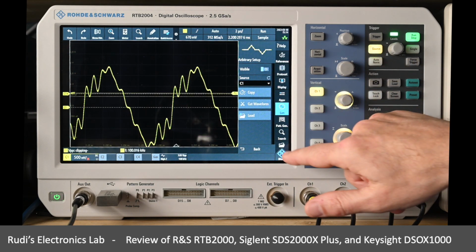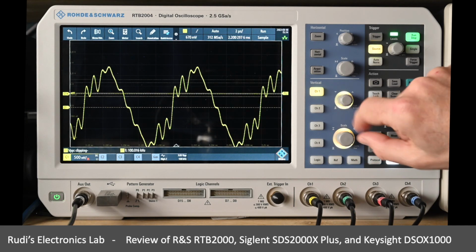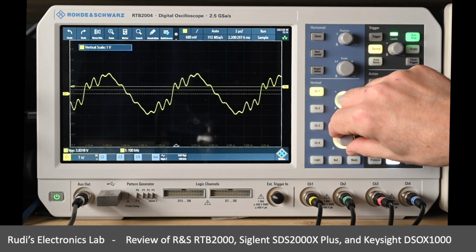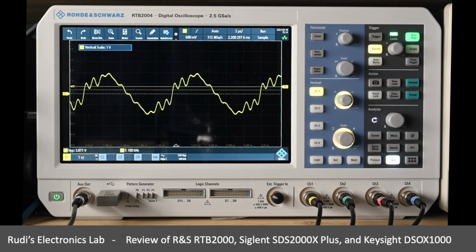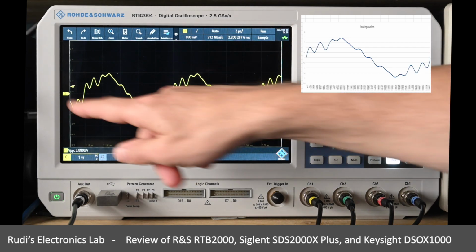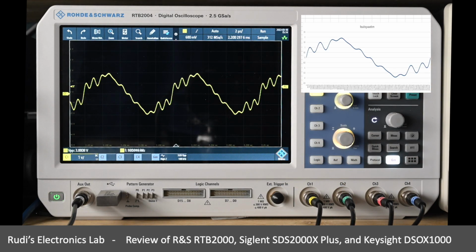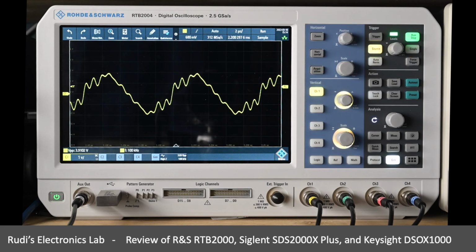So let's just take a look at channel 1 on the device. Let's put the wave in the middle, and there we actually got our waveform. So this is precisely the waveform as we also saw it in the Excel file. And actually now we're seeing slightly over 1.5 waveforms or so. In order to know whether this waveform really does have the higher harmonics that we were thinking about, we can also take a quick look at the spectrum diagram of this particular signal.